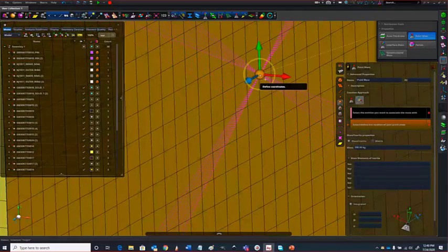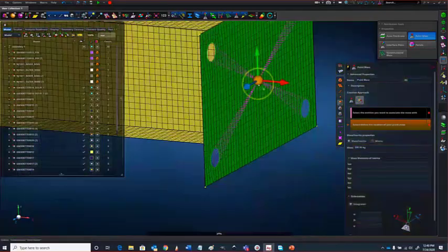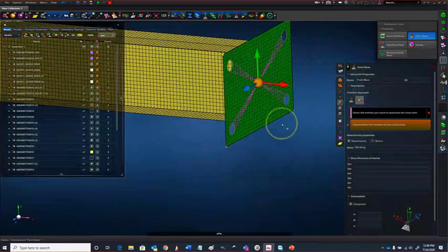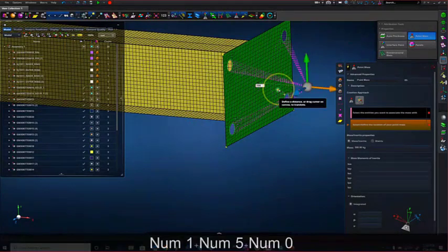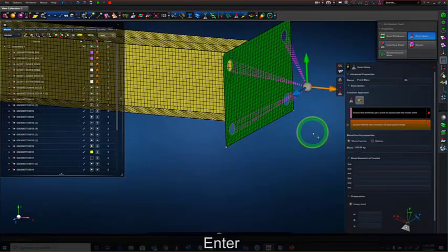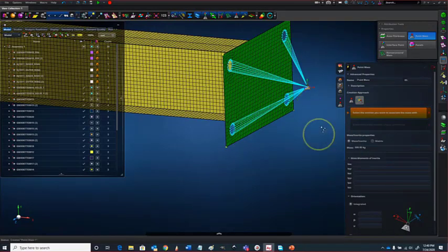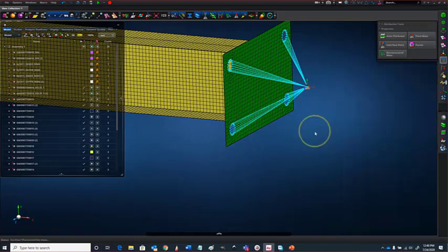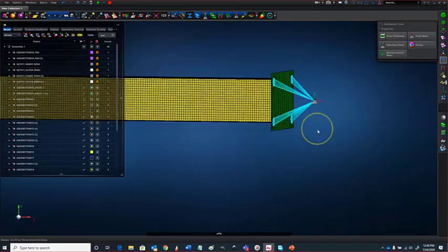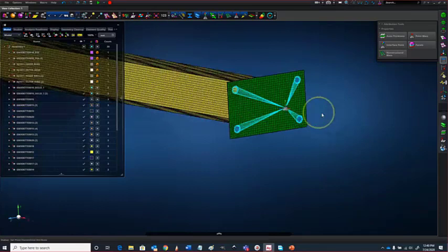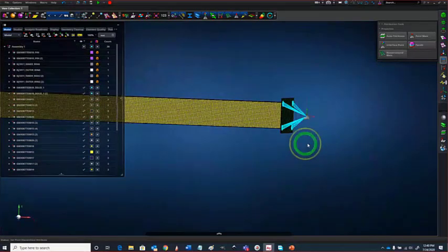There's the dot. And unselect that, select this guy, type in the offset value, middle mouse click, and what I missed previous time is the middle mouse click again to accept the default orientation of the body, and now I can exit. Okay, so now I have a 500 kilogram mass attached to those 5 holes over there.